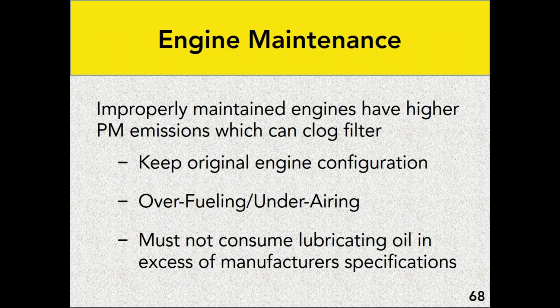The engine maintenance is key because an improperly maintained engine is going to produce more particulate matter, and that is going to clog the filter in a quicker manner than an engine that is properly maintained. This involves several things. Number one, making sure that you keep the engine's configuration. You pay attention to how the engine's operating. So let's go through those.